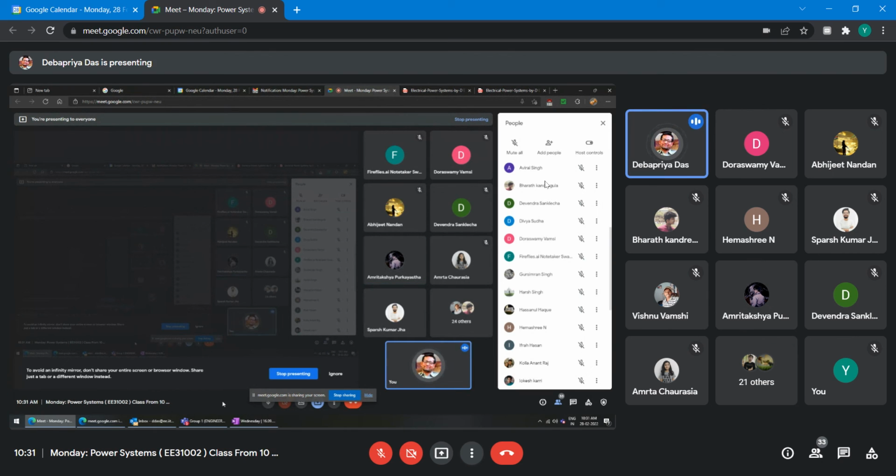No. Initially, suppose the slack bus voltage is given; in the load flow problem we generally assume all buses are PQ buses. Let me clarify one thing. I should not tell, but still I tell. I didn't give you any PV buses. PV buses will take more time in the classroom. So in this load flow problem I'm giving only PQ buses. Slack bus voltage is given.